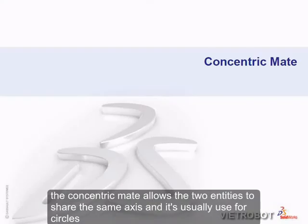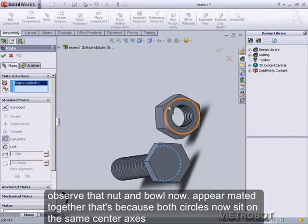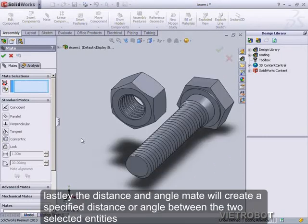The concentric mate allows the 2 entities to share the same axis, and it's usually used for circles. Select the 2 entities as shown and click on Concentric. Observe that our nut and bolt now appear to be mated together. It's because both circles now sit on the same center axis. Lastly, the distance and angle mate will create a specified distance or angle between the 2 selected entities.